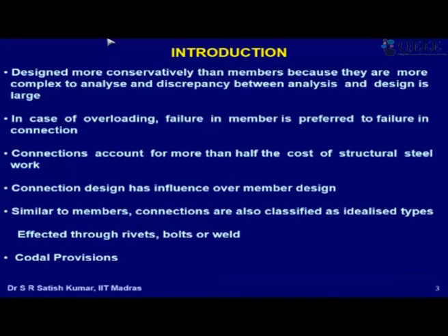We do have a margin of safety for working stress design, and also in limit state design we call it a load factor for variation in the load and material factor for variation in material. This material factor includes the discrepancy in the analysis and the real behavior. That is one of the other major issues. In connections, they are so complex that they produce a lot of stress concentrations, etc., that it becomes very difficult to account for all that.